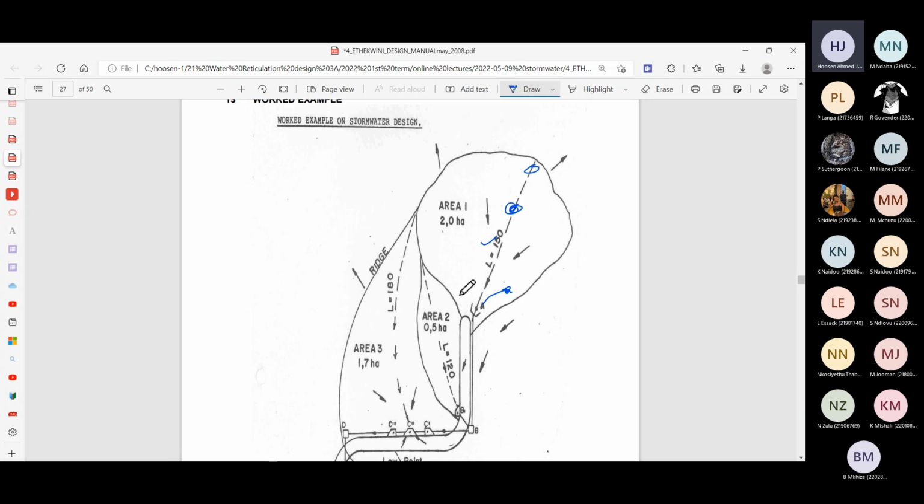So now you have flow from the entire catchment reaching point A at that moment in time, at the 23-minute mark. Even whether it's 24 minutes or 26 minutes or any period longer than that, it means that rainfall from every part of this catchment is now arriving at point A and would be flowing through that pipe. So that would be the most intense flow that you would get in that pipeline AB. And so that's our concentration time, 22.5 minutes.